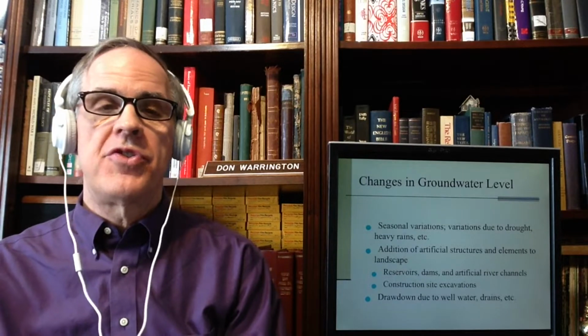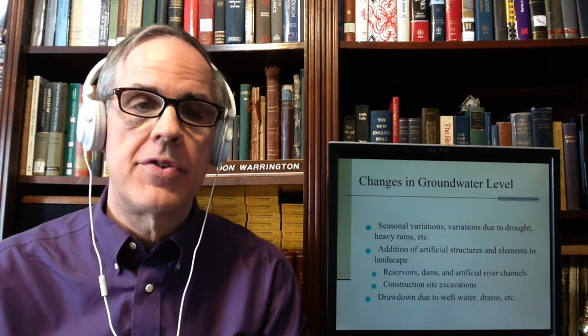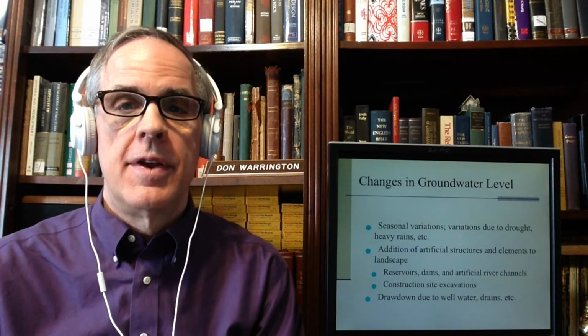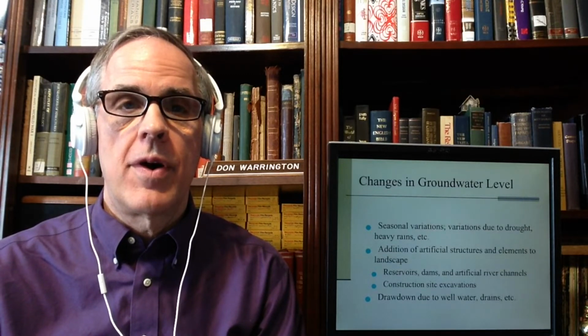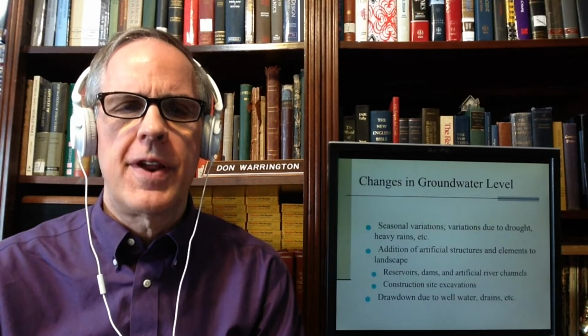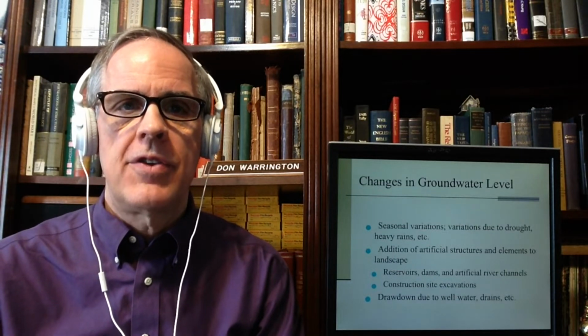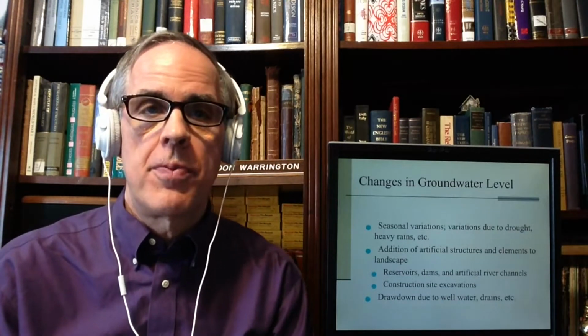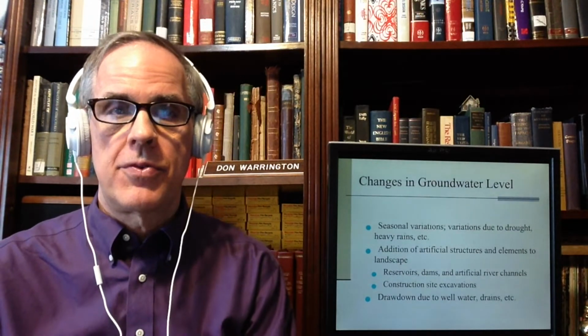Those water levels change. One of the things I touched on with boring logs is the fact that groundwater is not a fixed level. The phreatic surface is not fixed. It can change with seasonal variations. The structures we put on top of it definitely change groundwater levels.